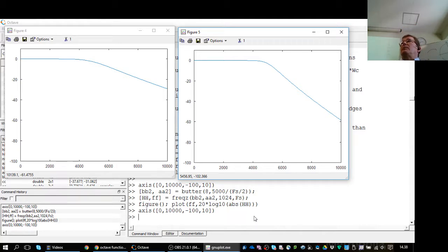There must also be a better way to define a filter. Remember the box. The box actually had the ripple, cutoff frequency, and also the transition bandwidth and attenuation. So how, other than by trial and error, to find the correct order number? Well, one easy way: 2 stages means 20 dB per, oh no, 20 dB per decade more attenuation. Okay, the same way as analog filters. So basically it's 20 dB when you add stages to the system. But anyways, let's do it the better way.